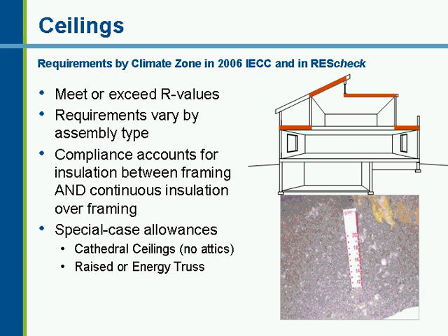So the code allows 500 square feet to be based on the lower requirement of R30. All square footage over 500 is based on the higher requirement.